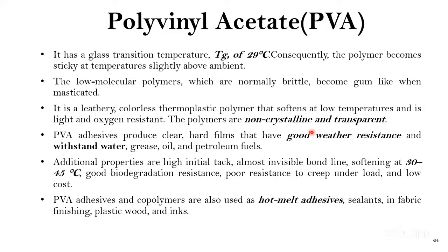Basically like a sample, right? Yes, you people say that as a sample. We call that a master batch. And then you just do the final processing. Suppose in injection molding, you do the final processing to get your product. Master batch will be a solid type, right? Yes, it is in solid granule form, or seed granules, whichever form you want. Generally in injection molding we give input as granular only. Powder also we get.